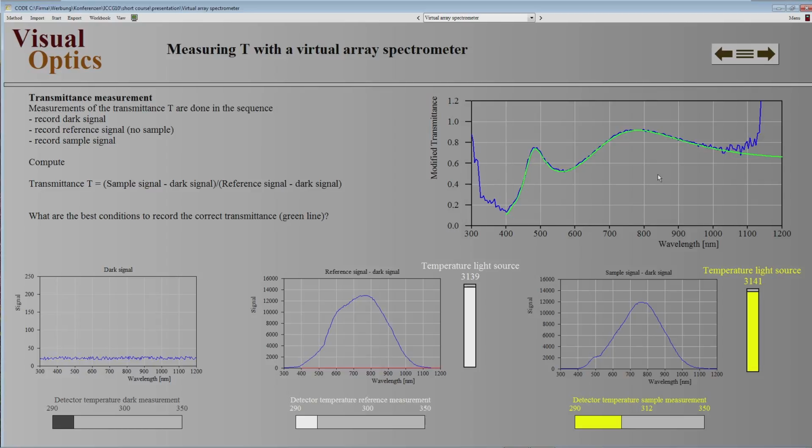And the second thing you should do is measure the reference signal and the sample signal with a small amount of time in between. Usually, after every pane, after let's say 40 or 60 seconds, your cycle time, you should measure a new reference, so that the time between those two measurements is only a few seconds or just a minute, and then it should work.